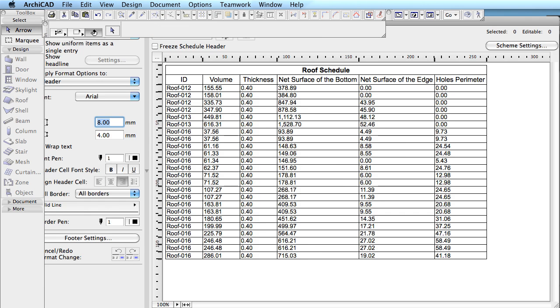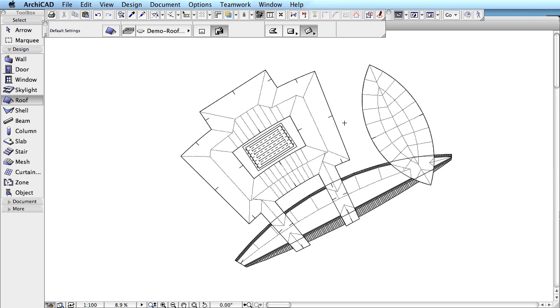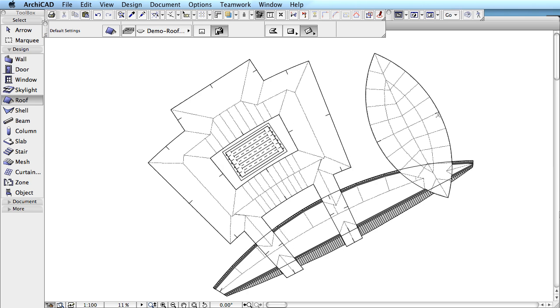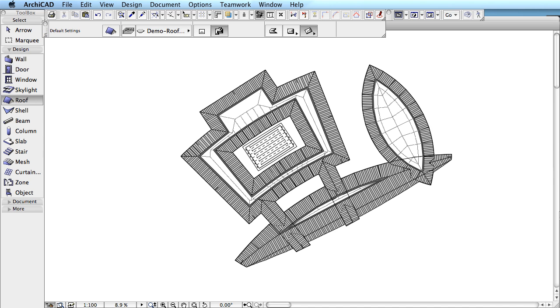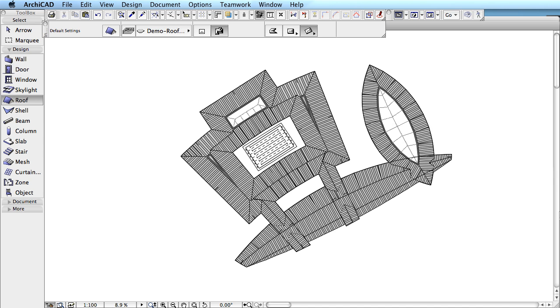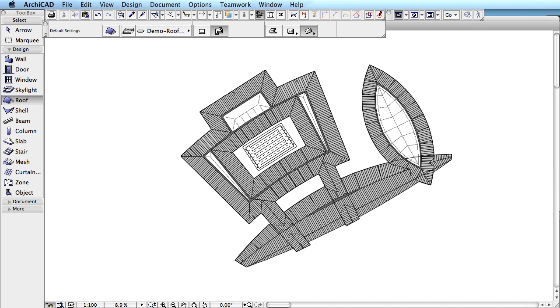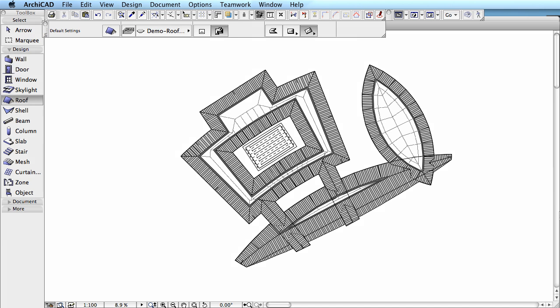Element schedules as well as quantity lists can be generated automatically. The representation of the roof systems are also integrated across the project. Floor plan, section, and elevation views are always created and maintained automatically. Even the cut surfaces on the floor plan views are represented correctly. Indeed, if different floor plan views are displayed, the representation of the roof systems will also change automatically and accurately according to the actual horizontal cutting plane.